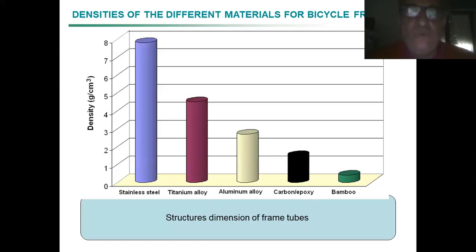Because, for example, when you involve metals, you normally weld the different tubes with each other. Welding is performed better at some angles than at some other angles. And with some thickness, some thickness are required. You may need to make your bicycle heavier than needed by the simple weight of the cyclist or the other force, just because you need to weld in a suitable way.